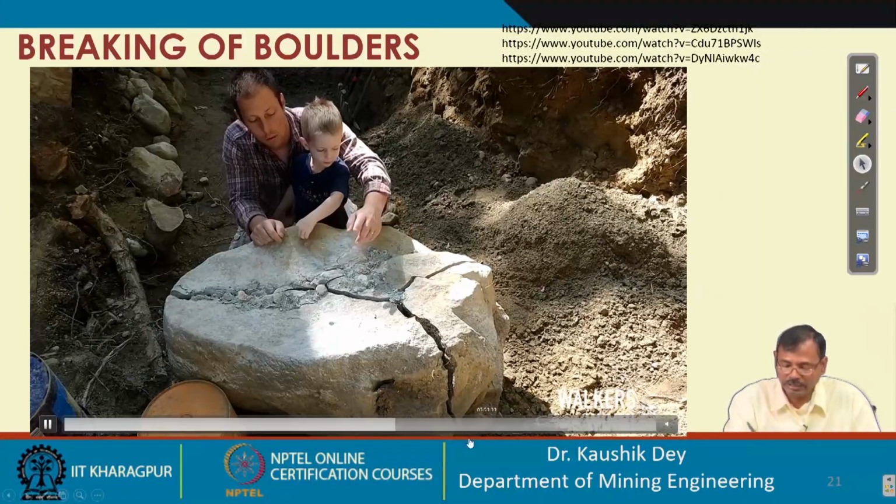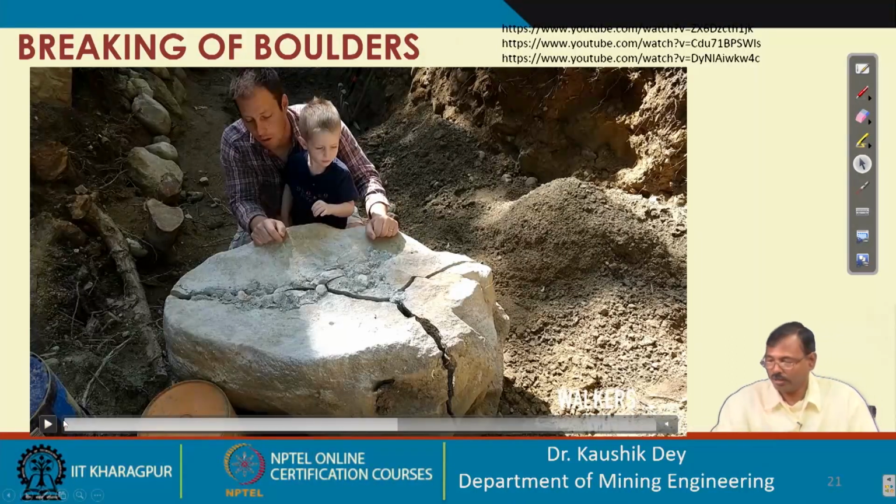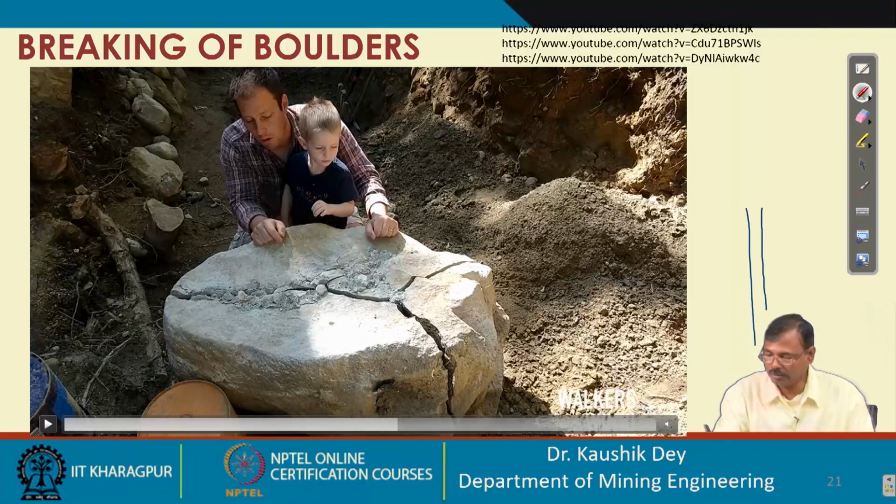So, basically, if the boulder, we have drilled this one, after that we place the expanding cement, and in all the cases this cement must be fully filled, because if there is a gap, the expanding cement will expand in that gap.